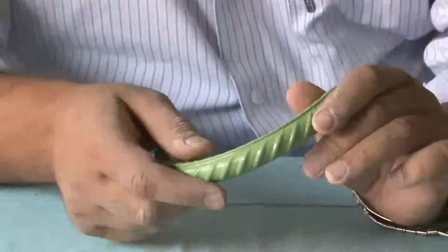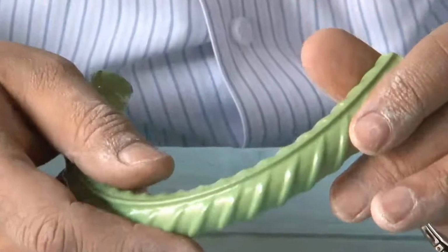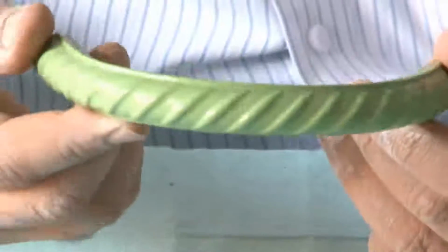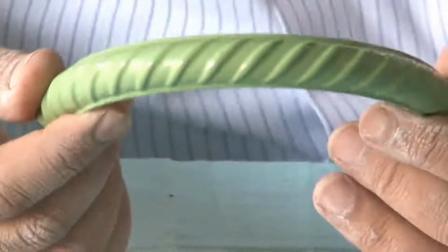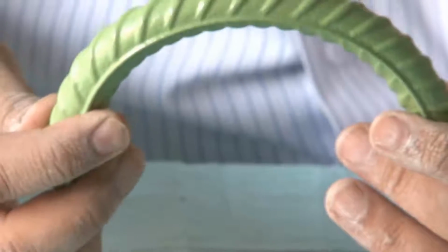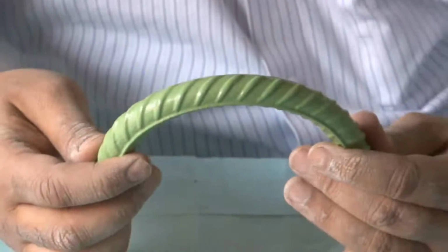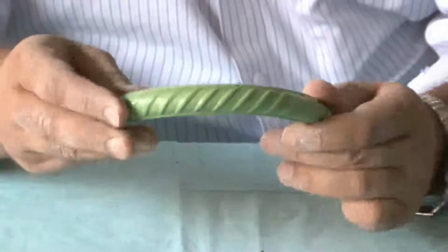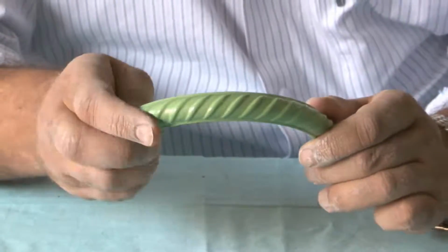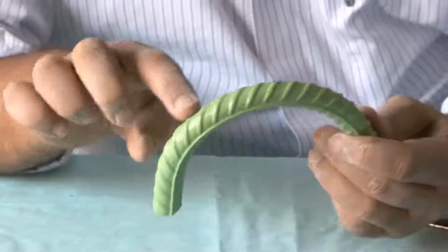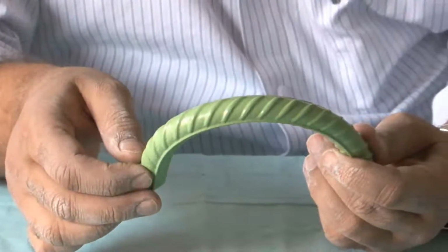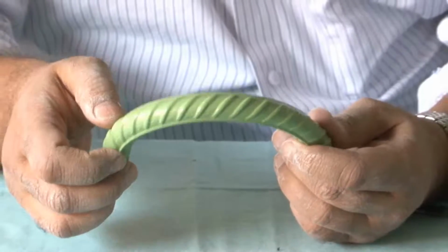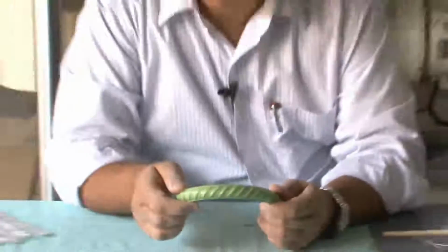Continuing our discussion with the epoxy coated bars, we know that in certain cases the bars need to be bent at site, which is shown here, and this is a bent epoxy coated bar, and we should be careful when we are using such bars to make sure that there are no cracks on the coating, because once we coat the bar and bend it, the outside surface here is subjected to tension, and the coating is likely to crack unless it has a sufficient amount of deformability.